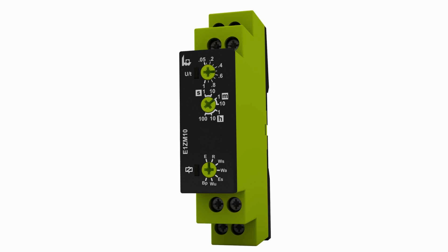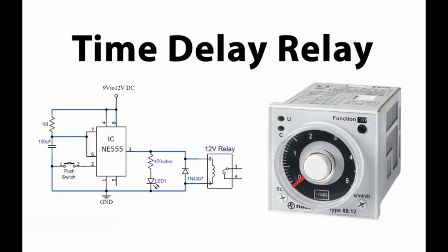Fast switching. Solid-state relays typically offer faster switching speeds compared to electromechanical relays. They can switch on and off in microseconds or milliseconds, making them suitable for high-speed applications. Silent operation. Since there are no mechanical contacts, solid-state relays operate silently without generating noise or vibrations.